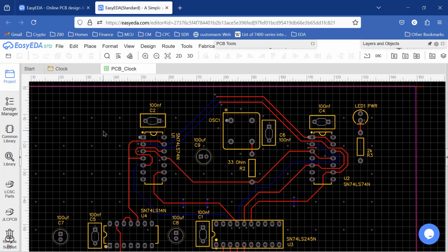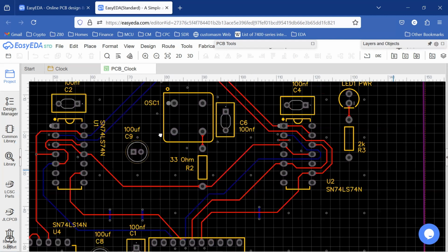So between those two things, the small solder pads and then the main clock signal running over those other lines, I really decided that I wanted to redo the design on that PC board, redo the trace routing. I didn't want to go through and attempt to solder up all the components, and then even after that do some board testing and find out that the signals weren't good because we were getting crossover between the main clock signal and those other two signals. So rather than going that route, I just bit the bullet and redid the whole board.